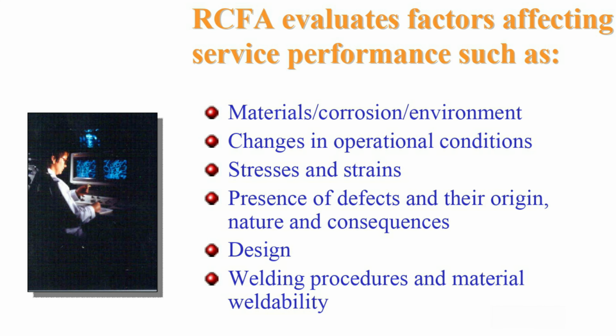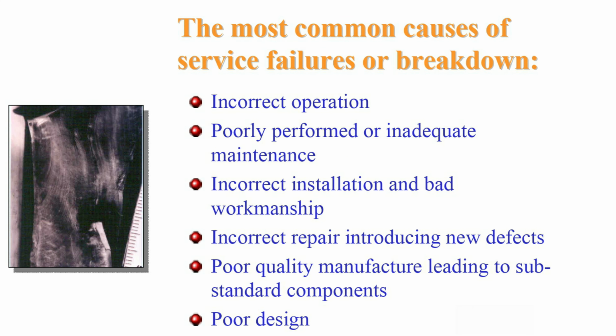RCFA evaluates factors affecting service performance such as materials and corrosion, and environment, changes in operational conditions, stresses and strains, presence of defects and their origin, nature and consequences. Design, welding procedures, and material weldability.